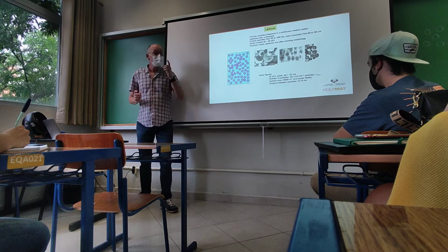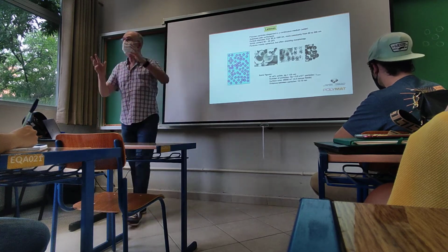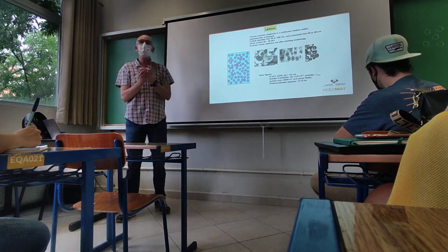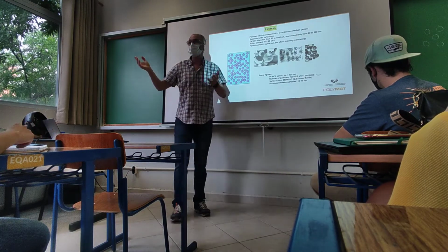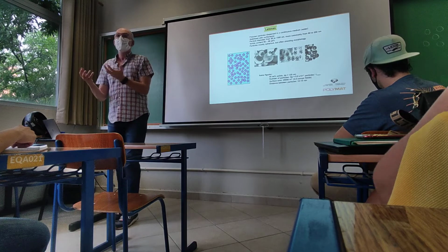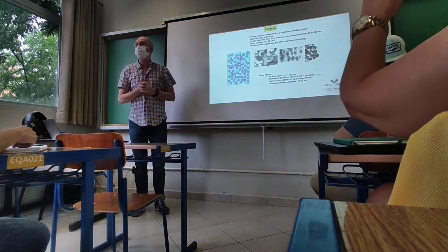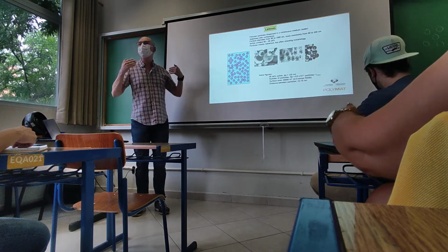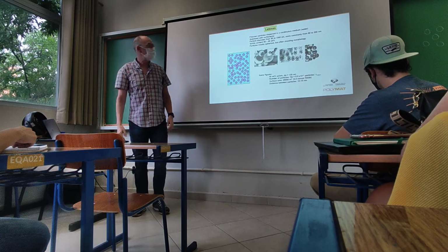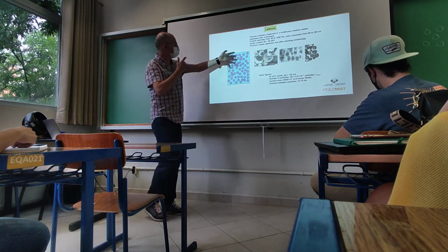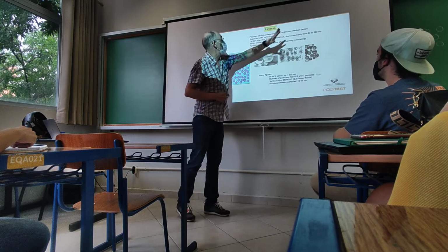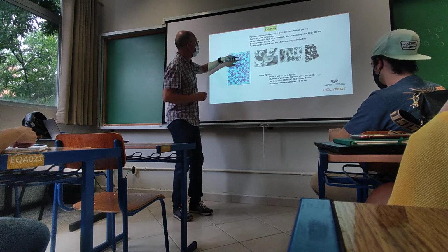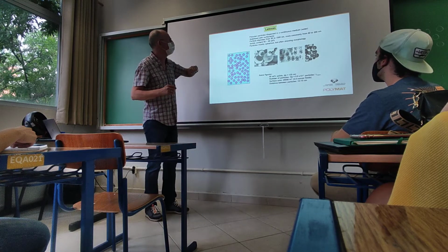Okay, the dispersion of polymer particles that we obtain in emulsion polymerization is called latex. And it's called latex because latex was the word that was used for natural rubber. So now we can say that these are synthetic latexes. Okay, this is a dispersion that you will obtain in the continuous medium, which is water, which is stabilized by surfactants, as we will see in a minute.